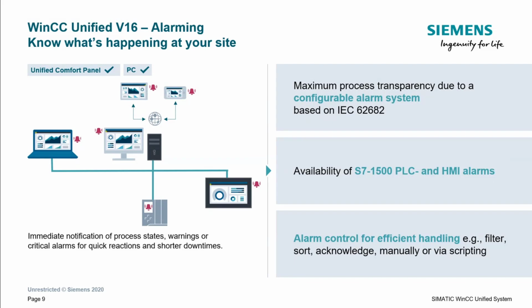so we're able to keep the operational efficiency of the machine as high as possible. So this is available on the PLC platform, the 1500, and also the HMIs in the PC stations. So the interconnectivity of the devices comes into play here. So you need to have, for example, a robust and reliable communications network, perhaps around Profinet, and this enables you to have this very diverse and interconnected alarming concept as we have here.